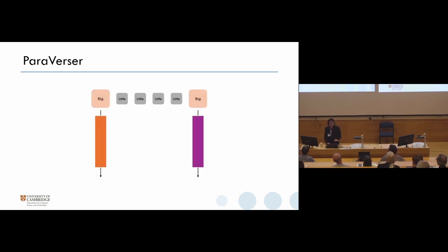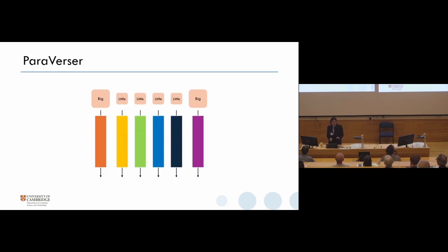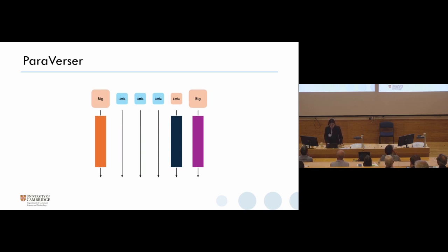In this system, both the big and the little cores can run the server workload without any problem. And we can also configure some of the cores to be checker cores. To check for any error, we first split the workload on the main core into multiple segments through checkpointing. And we can replay each segment onto a little core for duplicate execution. While these cores will execute the segments slower, multiple of them in parallel will keep up with the main core performance.